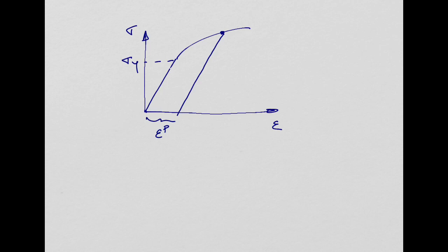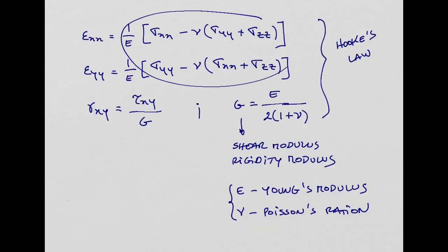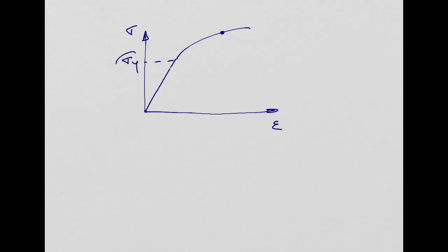Imagine you come to this lecture room, just your weight will induce a permanent deformation in the floor. So then you come tomorrow, after a couple of weeks, this does not look like a room anymore. So we don't want that to happen, right? So we need to make sure that the stresses we have in our plate, the stresses that come from this equation here, are below the yield strength of the material. If they are below, it means what? The material you use is able to carry that load.